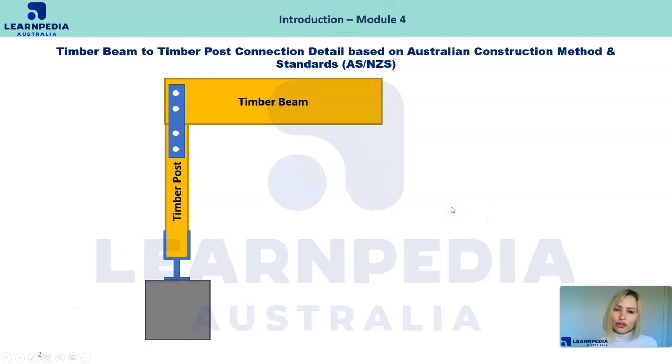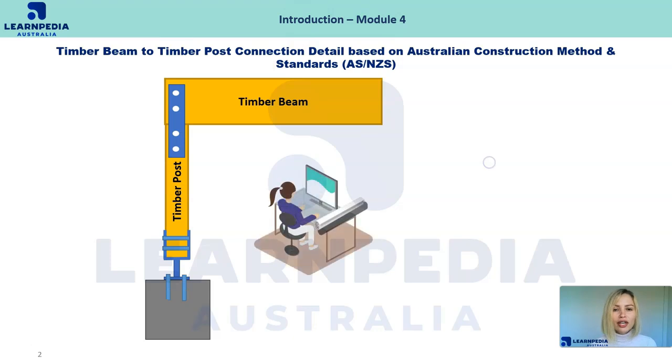You can use Pryda products, which were explained in Module 1 briefly, but I will run you through different connection details in Module 4 in detail. And how would you connect the product to the timber post using bolts, and to the footing you can use cast-in sets. So when you design something, when you put the drafting together, when you put the connection details together,